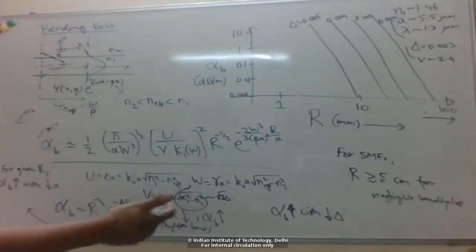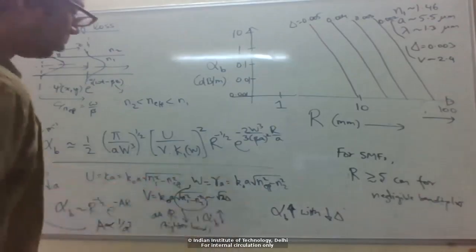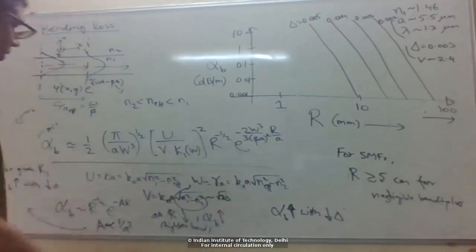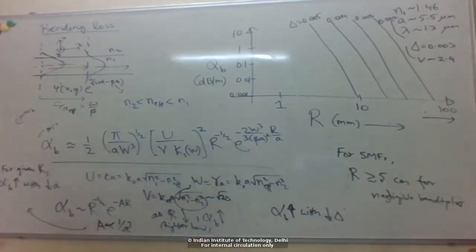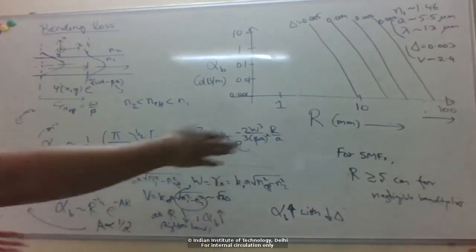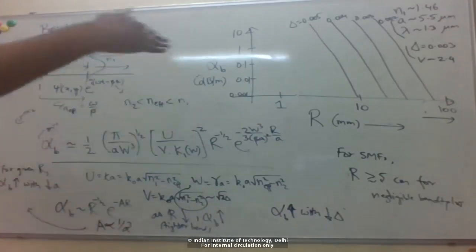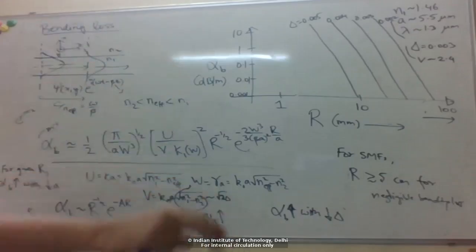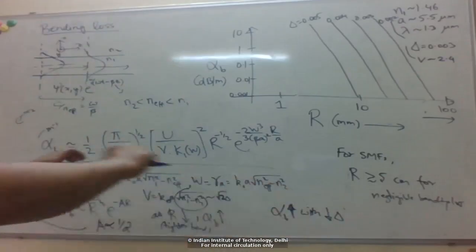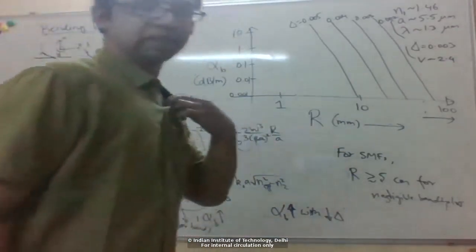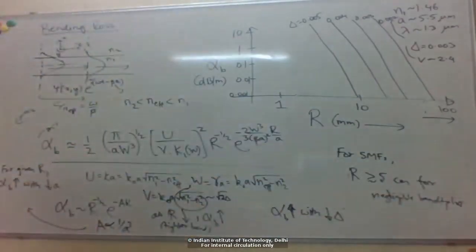Okay, so basically the take-home message is that you can't bend the fiber very tightly, right? Because that gives you very high loss. So whenever we want to change the direction of propagation of the fiber, the bend has to be over a large bend radius, so you have to bend smoothly. Typically, a few centimeters bend radius at least you need to have.